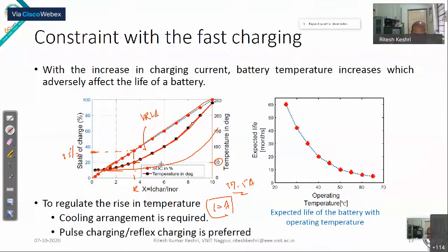It will take some more time. So what is happening? You can inject a lithium-ion battery with a higher current, 20, 40, 60, 70 ampere in place of 10 ampere. Because lithium-ion batteries have a low thermal time constant, you can inject higher current to have the same temperature rise. Like here, you have the same temperature rise.